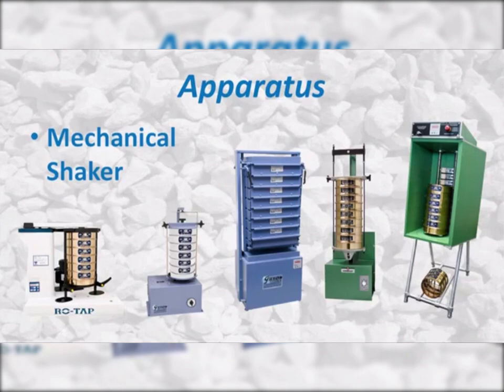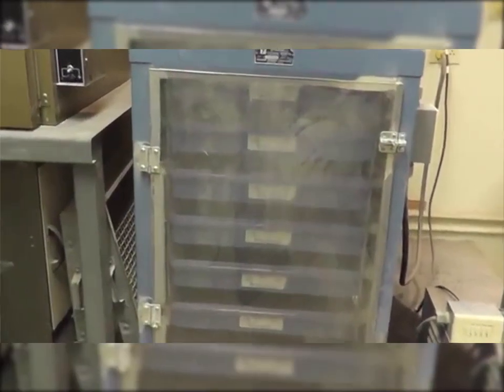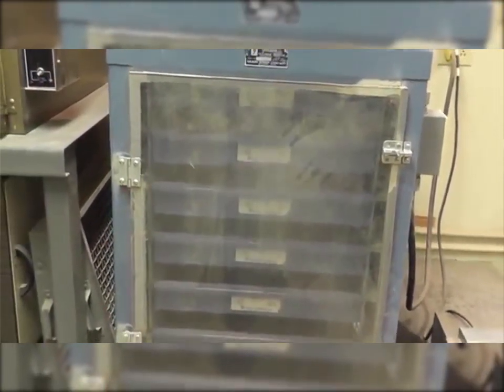If a mechanical sieve shaker is used, the shaker is required to provide a vertical or lateral and vertical motion to the sieves, causing the sample particles to bounce and turn so as to present different orientations to the sieving surface. Sieve shakers are required to provide sieving thoroughness within a reasonable time.